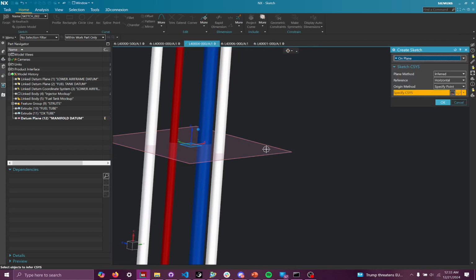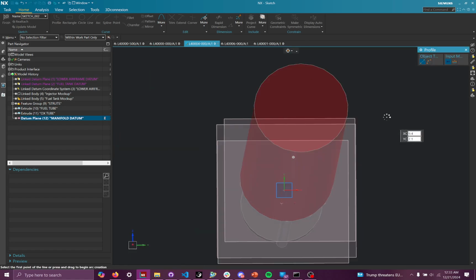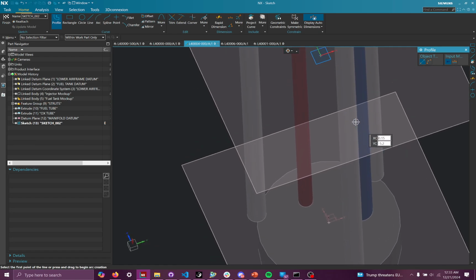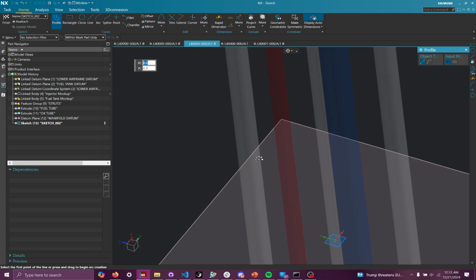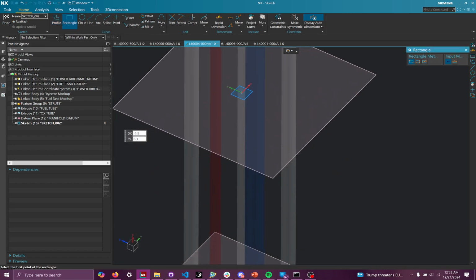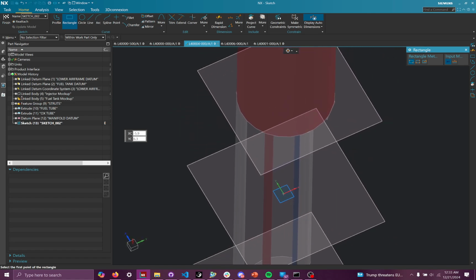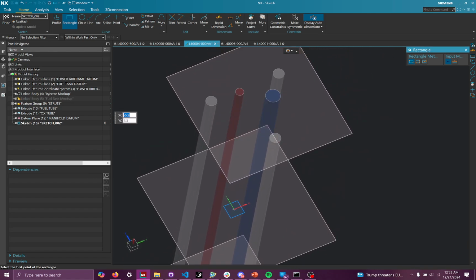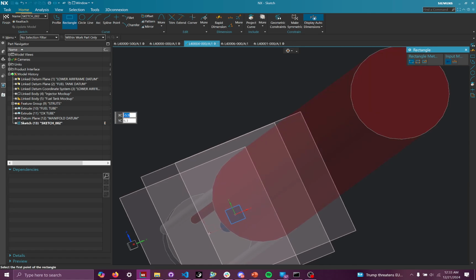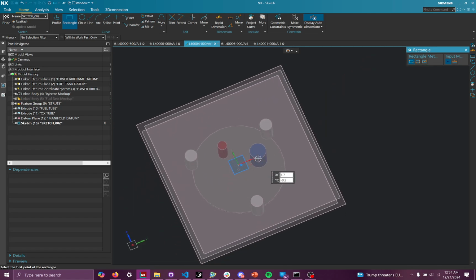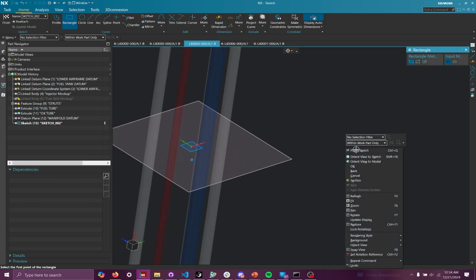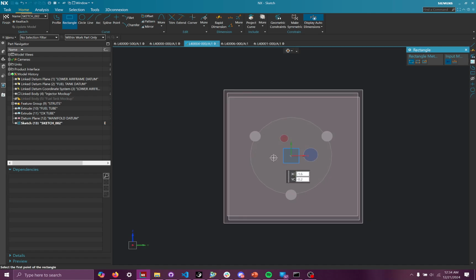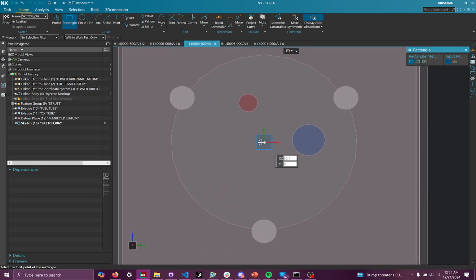So I'm going to create a sketch on this plane as one would, and I will make a very simple one. If you ever feel like you need to, you can hide stuff. Like I can hide this fuel tank mock-up linked body because it's getting in the way a bit. And I can orient the view to sketch so it aligns up properly.